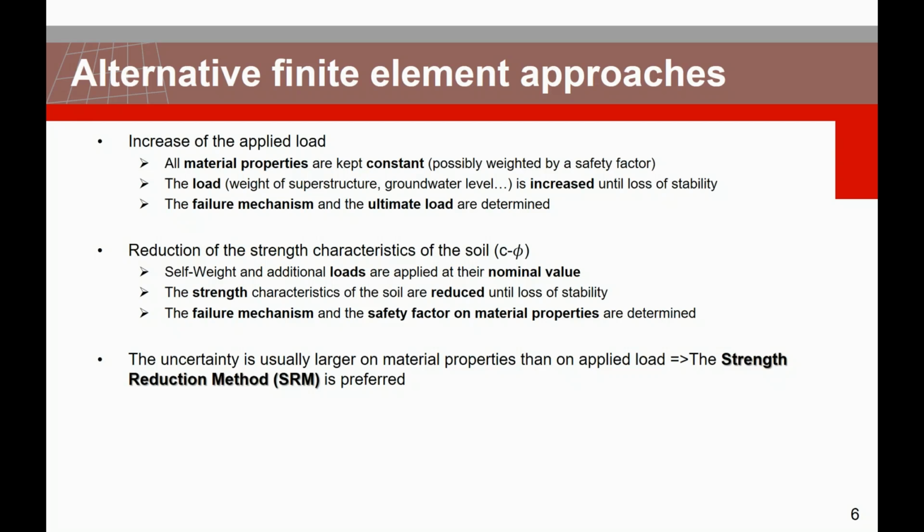The self-weight and additional loads are applied at their nominal value. The strength characteristics of the soils are reduced until loss of stability. The failure mechanism and the safety factor on material properties are determined. When you compare both methods, the strength reduction method is preferred. The uncertainty is usually larger on material properties than on applied loads. So the SRM method is definitely a must.